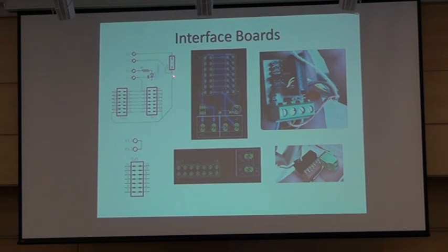So there's a jumper here for an even number of cables. If there's an even number of conductors in the cable where you want to test the shield, this is hooked into the shield, and then on the bottom connector here, connect back out.